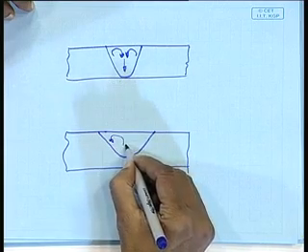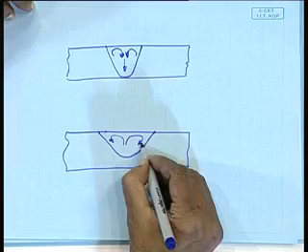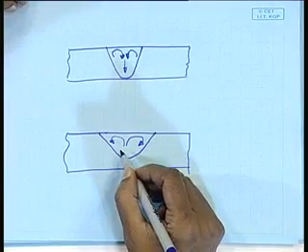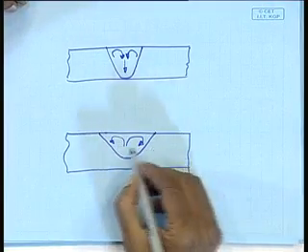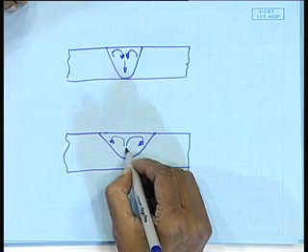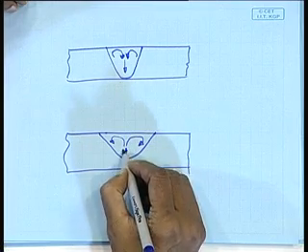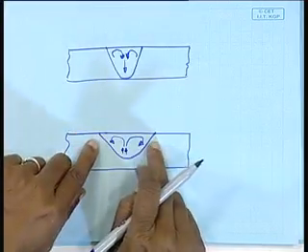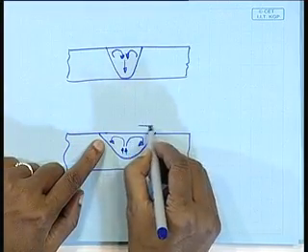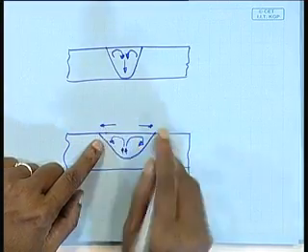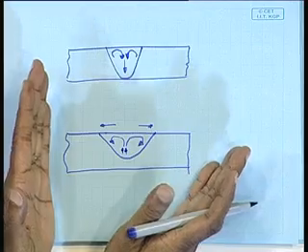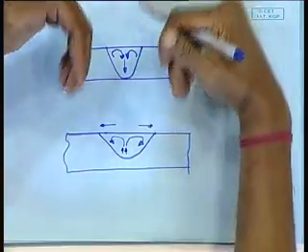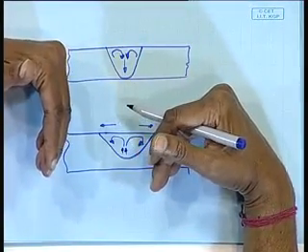the movement of the molten particles is just the opposite, as if it is going from the bottom and taking an outward motion, then the heat is conducted more on the sides, the wall fusion is more, it becomes wider, whereas in the other case it becomes narrower and deeper.